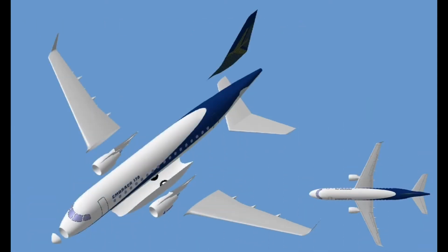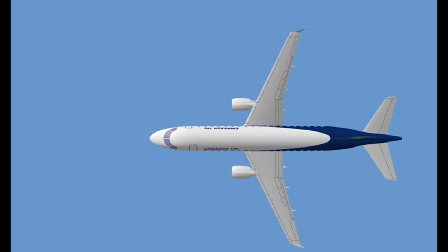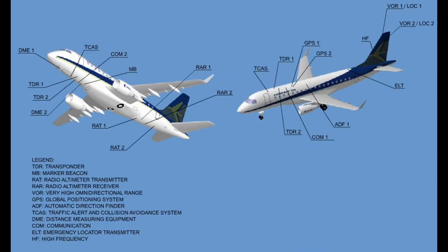To maximize performance, a variety of modern composites like fiberglass and carbon have been used. These materials are lighter in weight and more durable than conventional aluminum, improving aircraft performance. Besides the conventional flight controls, the aircraft is equipped with an adjustable stabilizer and multifunctional spoilers. Aerodynamic characteristics are enhanced by leading-edge slats and ground spoilers. The aircraft antennas are located on the fuselage and the vertical stabilizer, as shown.